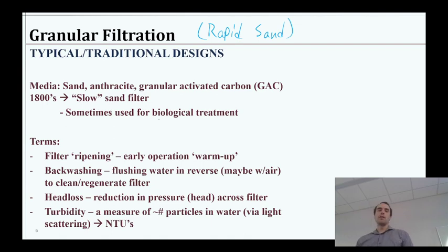Because if you let it sit there long enough, you'll get the biofilms, you'll get stuff growing, and we could treat wastewater that way in some sense. So if you had river water and you had no better way to treat it, in the 1800s or something, maybe that would make sense, to let whatever biological growth on these sand grains eat whatever organic matter's in the water.